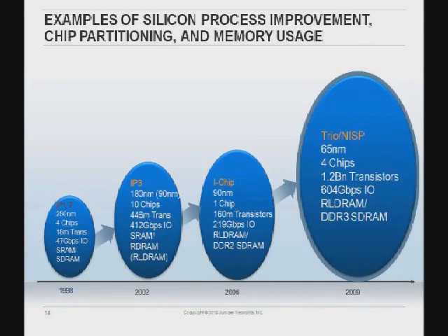In that case, we used SRAM as a control memory again, and we caught up in the RAMBUS thing, so we used RAMBUS as the data memory at that time. That's the only time we used RAMBUS memory. Later on, the original chip was designed for the T640, and we doubled the performance to the T1600. Then we did that chipset in 90 nanometer.